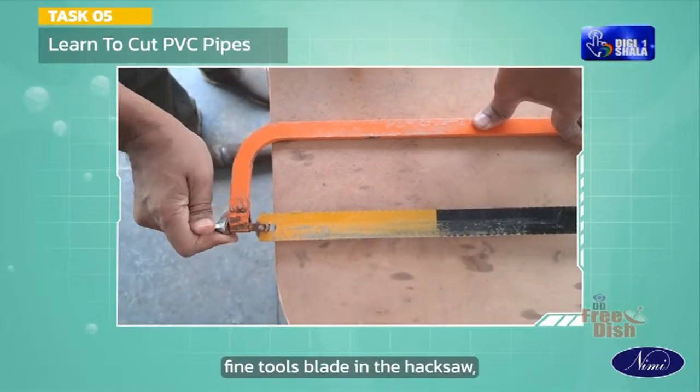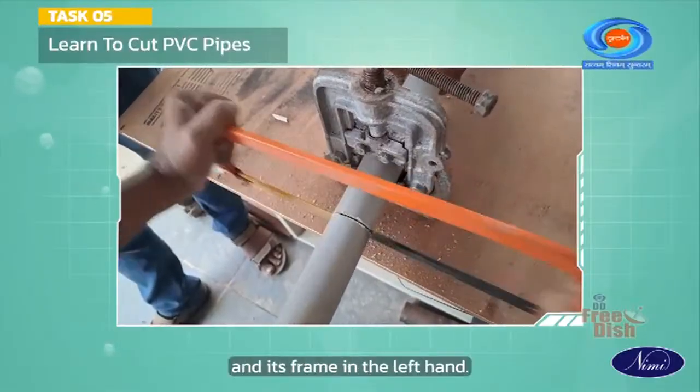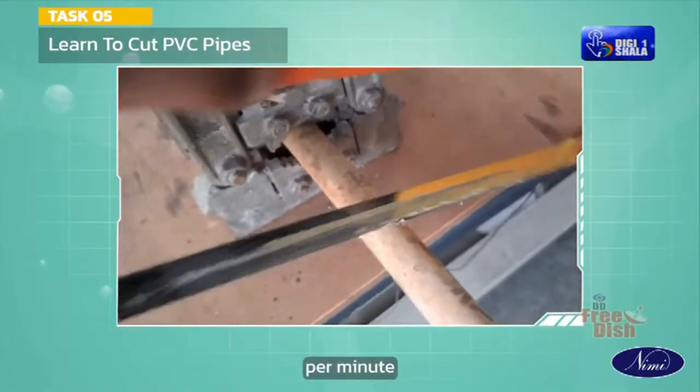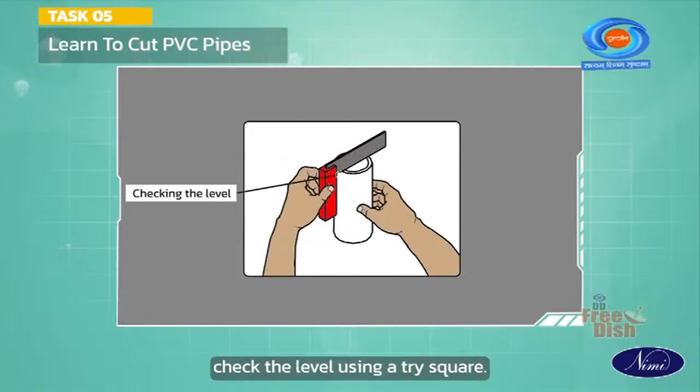Fix the fine tooth blade in the hacksaw. Hold the hacksaw in the right hand and its frame in the left hand. Move the blade to and fro on the mark and use 40 strokes per minute for the full length of the blade. File the edges with a flat file. Check the level using a tri-square.